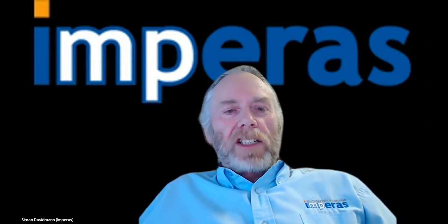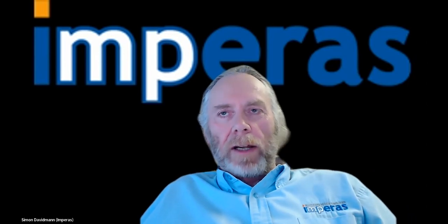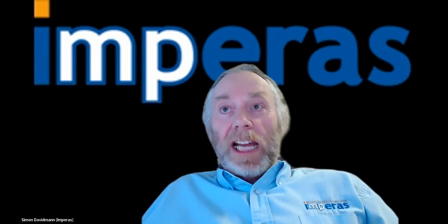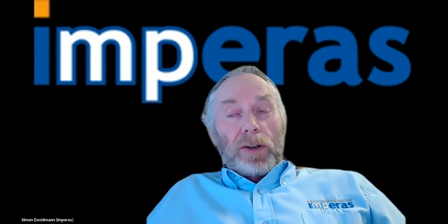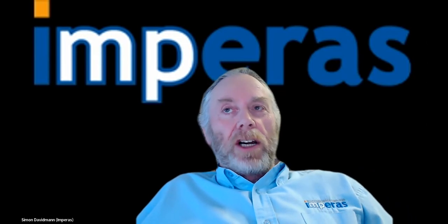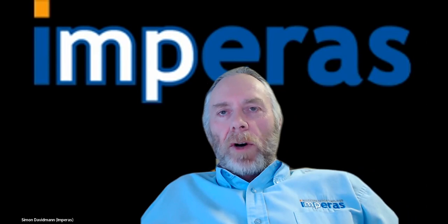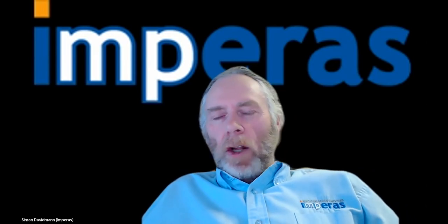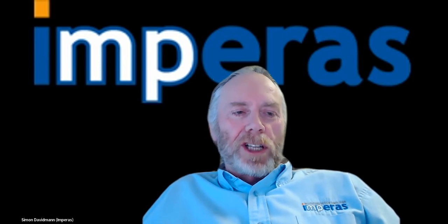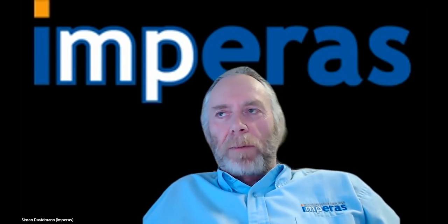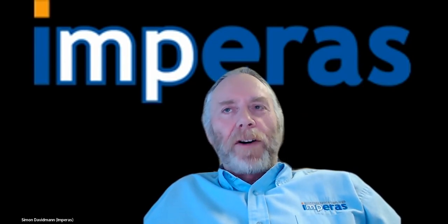In terms of vector processors, that is a relatively new thing that people have been verifying. I alluded earlier, when talking about the tests, that a couple, three years ago, we were engaged by a company doing a very large vector processor to help them write tests and do verification. We've created a lot of tests and there's quite a lot of experience in using those. When it comes to verification of vector processors in RISC-V, there are several options that are configurable in the specification, for example what happens with interrupts and exceptions. So it can get very complex.